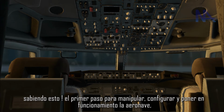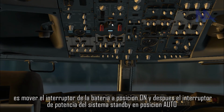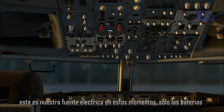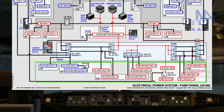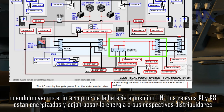Knowing this, the first step in order to manipulate, set up and put the aircraft in function is to move the battery switch to the on position, and then the standby power switch to auto position. This is our electrical source at this moment, just the batteries, and all these buses are powered now. When we move the battery switch to the on position, the relays K1 and K8 are energized and let the power pass to the respective buses.